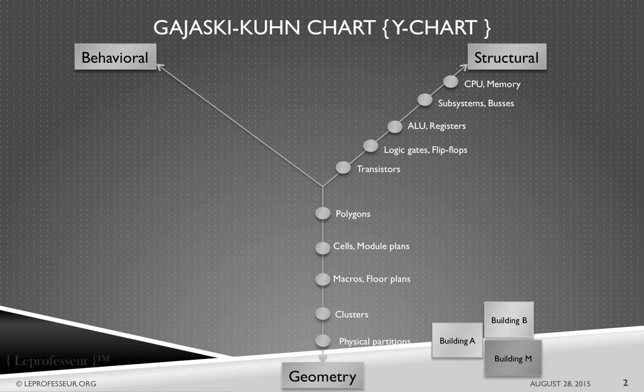And then if you tear a logic gate apart, what will you see? You will see small transistors. Good. So the transistor becomes the basic unit under the structural dimension, which corresponds to polygon. Actually, you make a transistor at a circuit level, and then you draw polygons to make a floor plan, or how in physical reality it is going to look, where the polysilicon layers would be, where my metal layer would be for one particular transistor. Good.